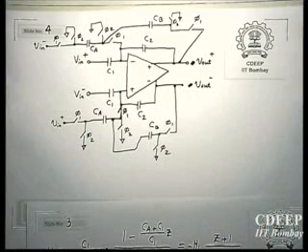Now, if we don't want to use this extra area because of double the number of capacitors, and the single-ended signal to noise ratio that you derived is enough for you, then you use half of the capacitors everywhere. Now you will have the same signal to noise ratio and your area will be less. Everything in switched capacitors depends on the ratio of capacitors, so you can easily scale all of them by a factor of 2.